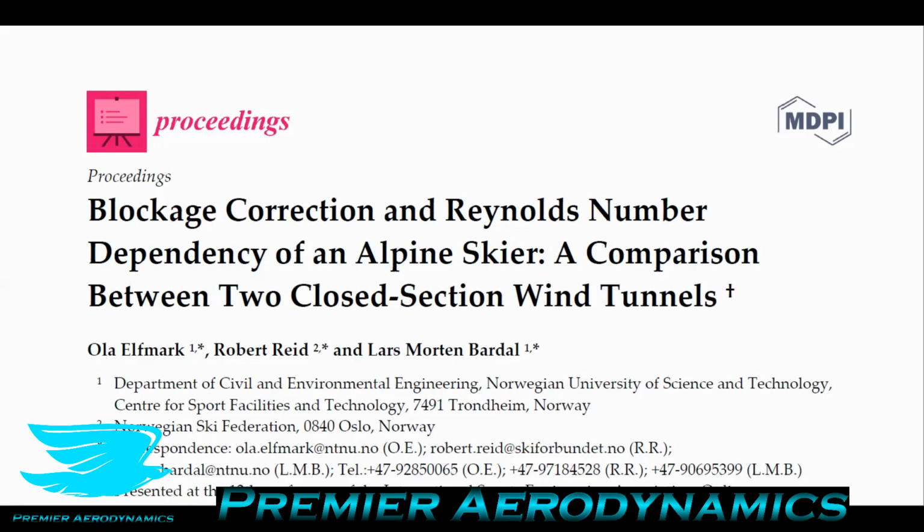And to do that, we're looking at a paper called Blockage Correction and Reynolds Number Dependency of an Alpine Skier: a comparison between two closed-section wind tunnels. It's an open access paper, so you can find it in the link below. The reason why I chose this paper is because it does a pretty good job of keeping variables constant between two different wind tunnels of significantly different sizes and operations, and it's of an object that is fairly representative of a wide number of applications.